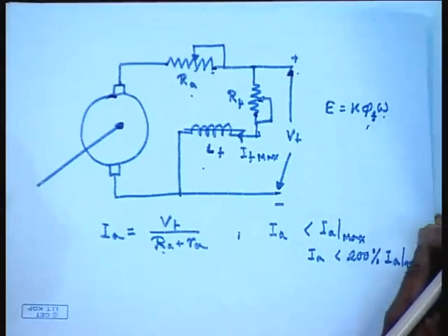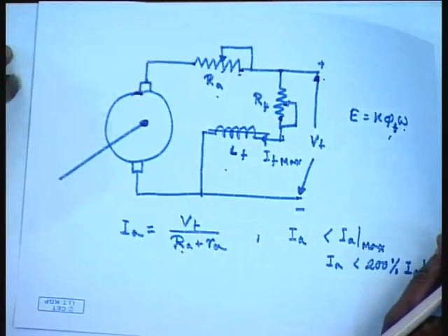However, as we mentioned that it is difficult to get a continuously variable armature resistance, therefore, step resistance starters are normally used for DC shunt motor starting. We will explain the working principle of one of them.